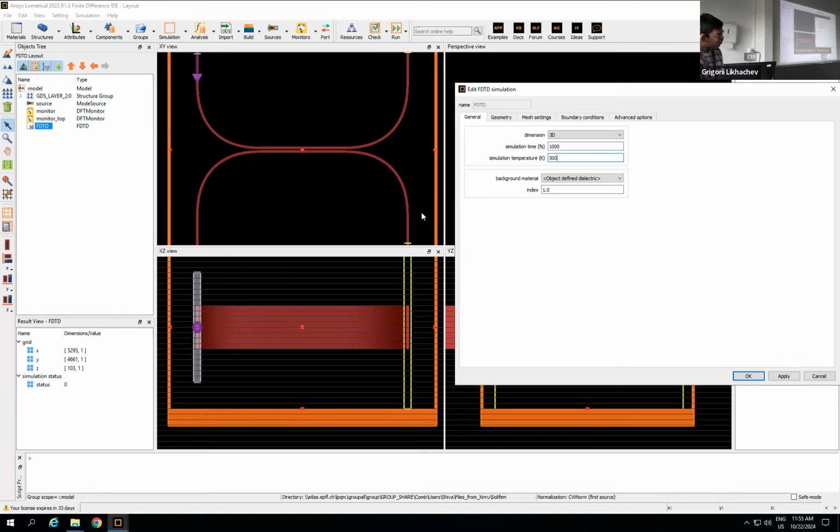But then again, we are using boundary conditions over here, so we would ideally like all the electric and magnetic fields to be absorbed so that we are sure that we get a stable solution. There can be some reflection over here and then the electric field comes back. We don't want that. We need to be sure that our solution is accurate. So we would like the electric fields to die down. So what we would need to